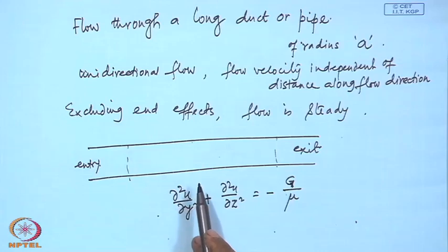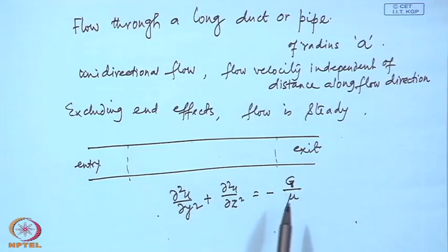Now, from our physical observation or from general sense, we can say that this flow when developed is basically axisymmetric, that whatever the theta is in any particular theta direction, the flow will be the same in all theta directions. There cannot be any theta dependence.